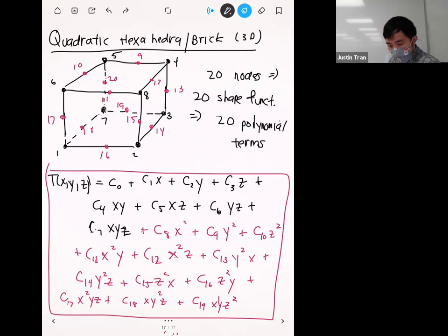Yeah. And so that's why, when you can swing it, and if you're able to do it from your ANSYS, and you can use a quadratic hexahedron, then this is the one I think that gives people most confidence in your results. Okay, just because there's just so many different variations that you can do here.